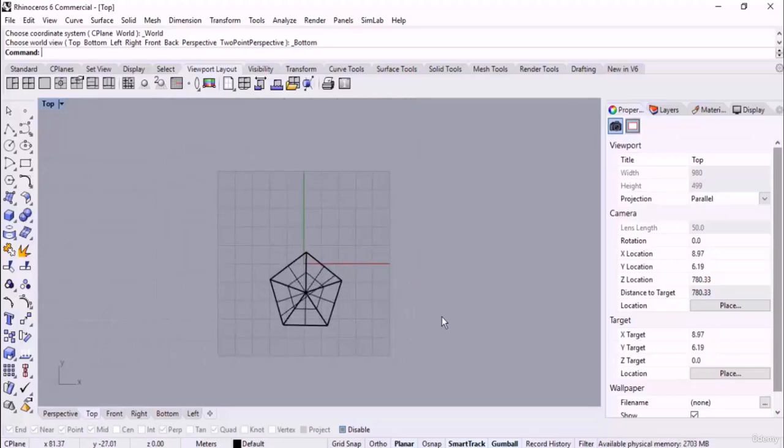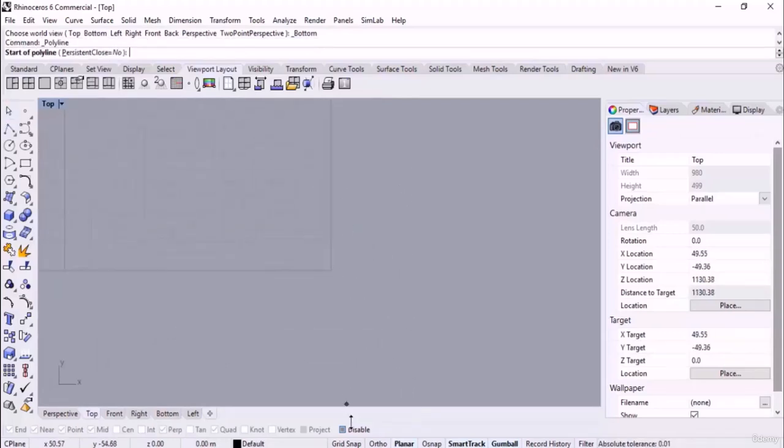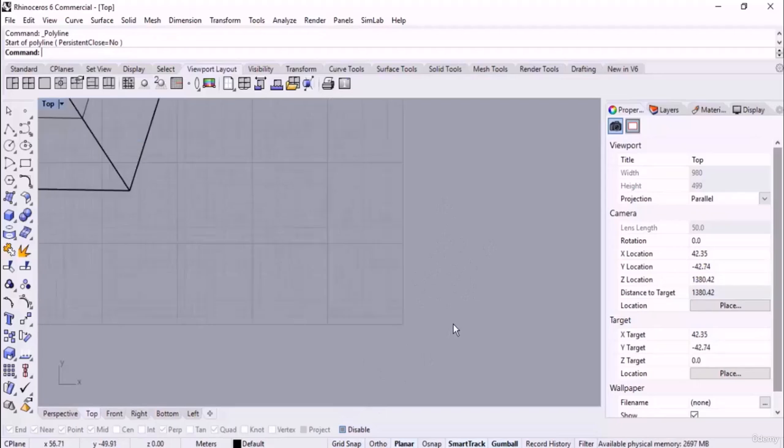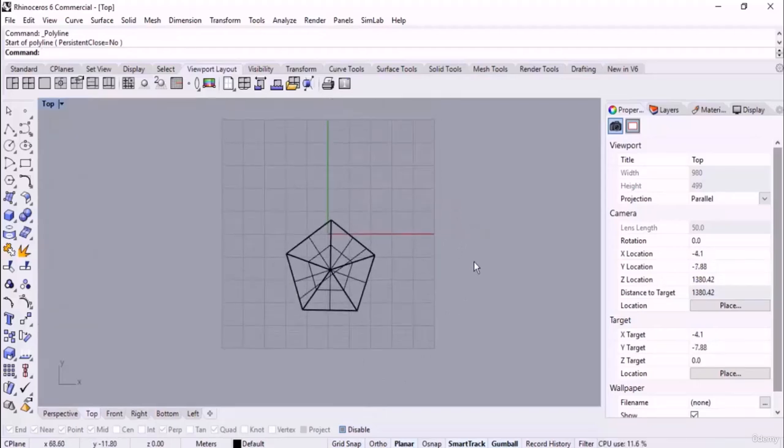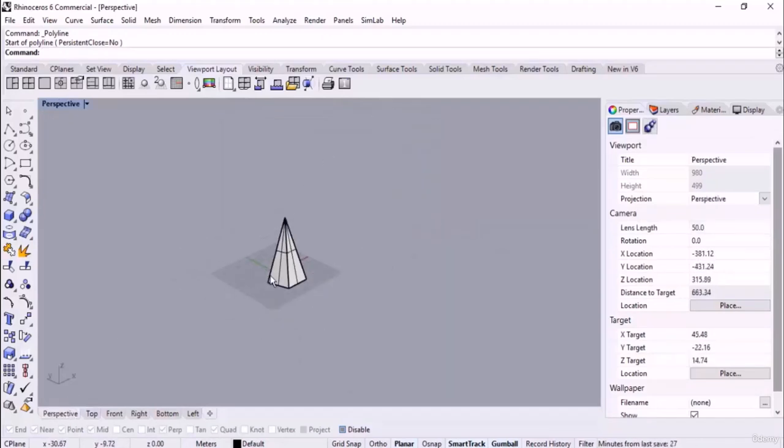Another point is that the boundaries of the grid lines are endless, or infinite actually. I mean, when we are using these object snaps, as you can see, we get the grids as well here, which shows that we have the grid lines everywhere since they cover the entire scene. As I told you, we can control the visibility by using F7.